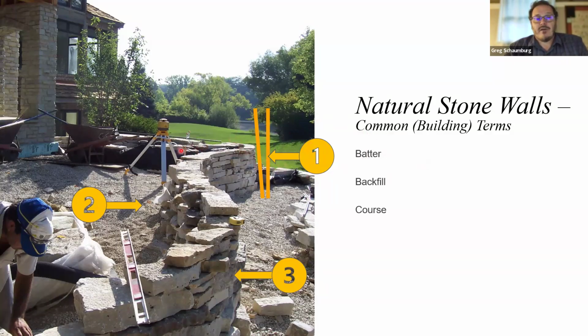The other part is backfill, and you'll see that this wall essentially is this curvilinear form. It's all of a limestone origin, and it's semi-coursed and semi-consistent. But what you'll notice is that this area down below, which is going to have some steppers and some planting in it, is way below this part. Finished grade will be about 28 inches or so from one to the other. So there will be a patio surface up in this area here, and everything that's going behind the wall is lifted up in compacted levels of gravel, and that's our backfill.